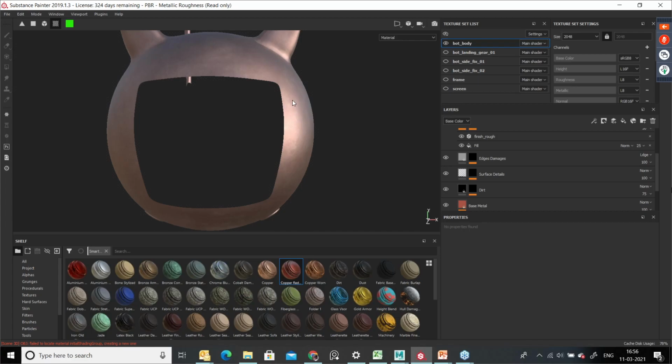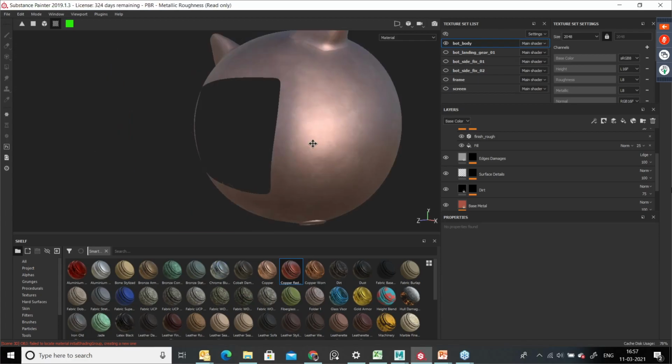When you bring it into Substance Painter, if you want to see the inner portion of the geometry, or apply texture inside the geometry, then you should use an extrude method or a duplicate surface, so that the normal is available on both sides. In that case we can apply texturing inside the geometry. Otherwise it will be like this only. Okay, yeah. How to create a texture set list? Texture set list should be done in Maya, so I already explained.